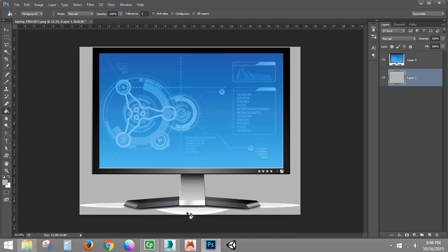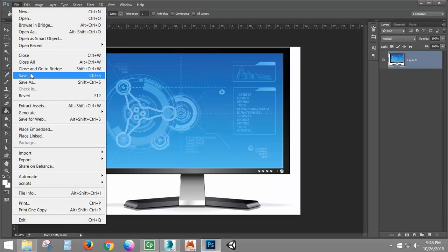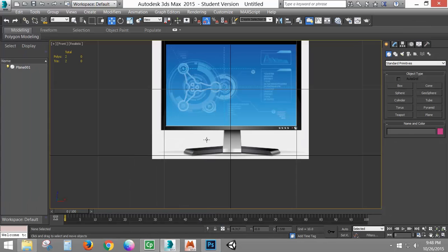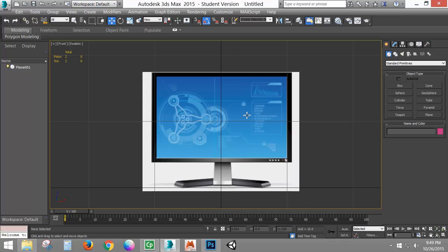I'm not worried about this white that I'm getting here. That's based on the image that we pulled from. I could use white, you know, I could sample the color from here and paste that in if I really want to. But I'm going to press Control E to flatten this, and I'm just going to resave this PNG. And when I do that, it's going to get rid of that transparency, and it fixes my image. So now I'm not seeing anything weird here. So be careful with PNGs with transparency, bringing those in as references. So that's our starting point here.